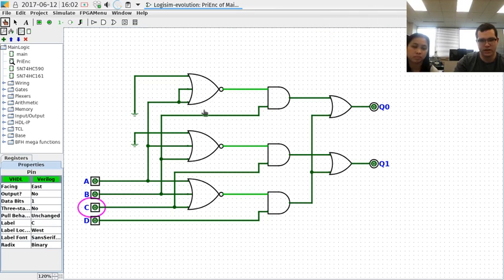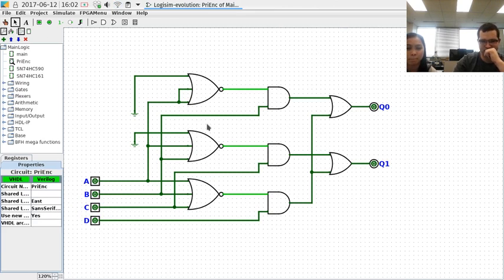This here is an inverter. It's just wired as an inverter. It's a NOR gate with its inputs tied together. And then the rest is just some combinatorial logic to actually get that done. You might wonder why we chose NOR gates, and the reason is actually a practical reason. It's that NOR gates were cheap, essentially. We could easily get a package with 3 NOR gates in it, and so that's what we used.